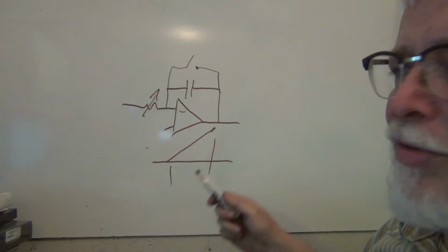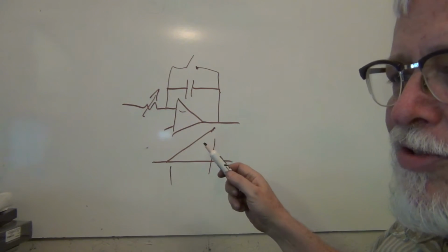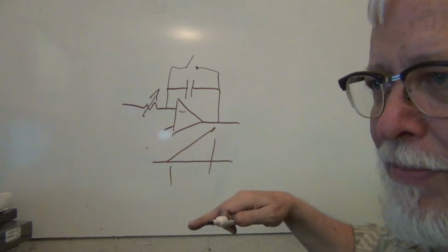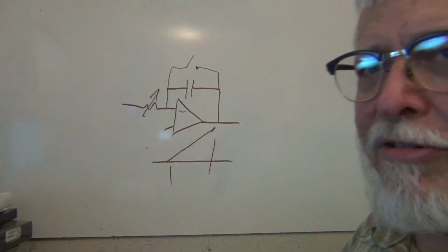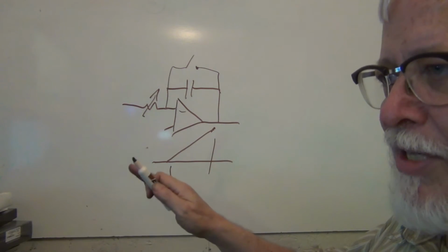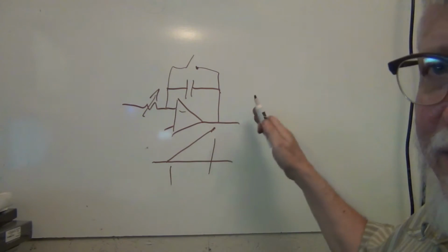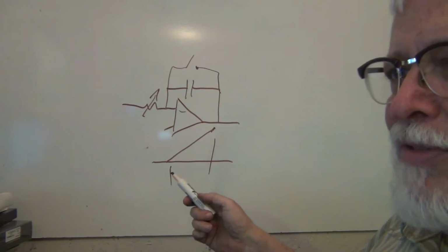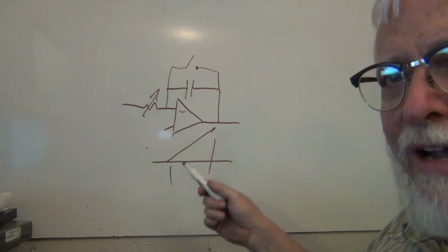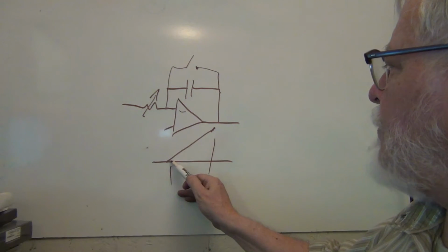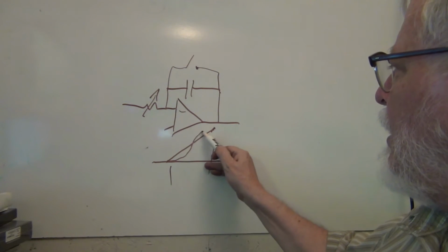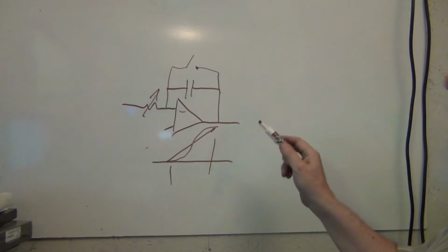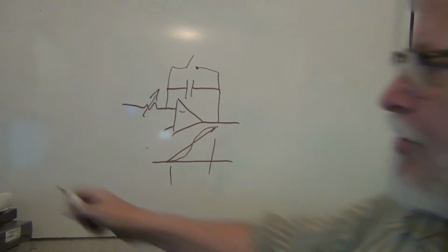So a ramp generator can be used to generate a horizontal sweep or a vertical sweep, and a raster can also be used to do an animation. And a lot of times in an animation, you don't want just a straight line move between keyframes. So a lot of times they use a sine wave function in the ramp generator, which gives it a slow in and then a slow out. I hope you can see this all right. Okay, so that's a ramp generator.